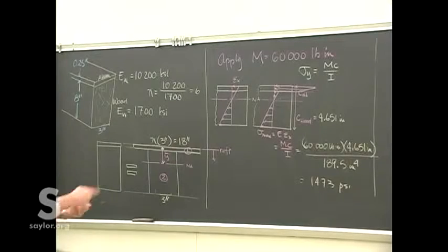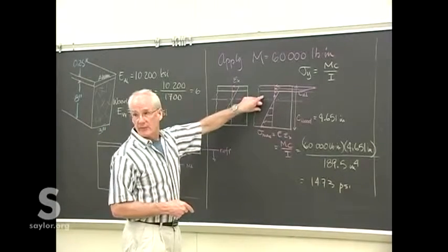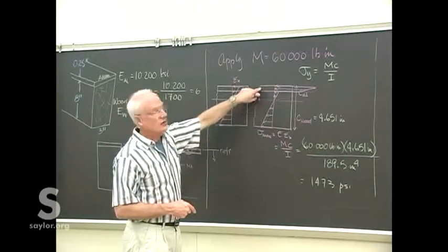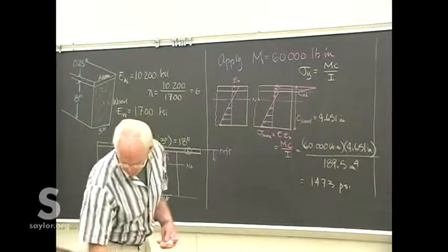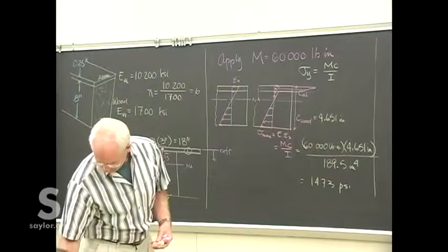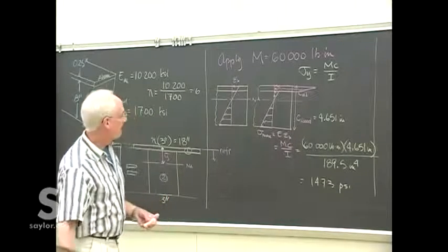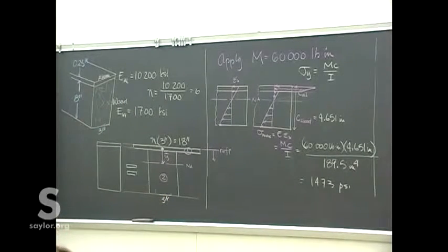Might have been that for that load, the wood would not have been sufficiently strong. So you put in an aluminum plate across the top that absorbs a lot greater stress, and then put the wood on the rest on the bottom for perhaps aesthetic purposes or for weight purposes. And we've got the whole picture there now.